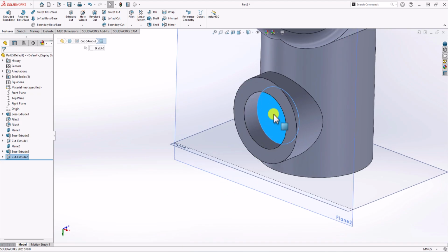If you want to achieve this flat surface, because according to section A, you can see that that surface is flat in section A, this is a solution you can have. First, you need to extrude 9 mm, then you need to make this cutout to achieve this flat surface. So I hope this is clear here. Okay, let's go to the next step.